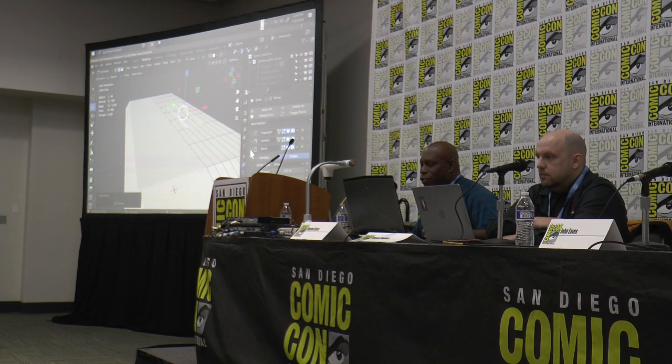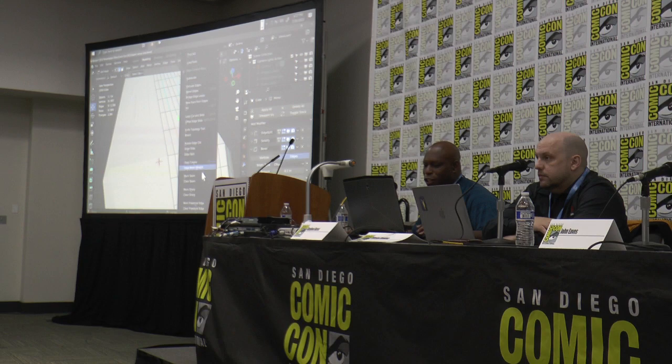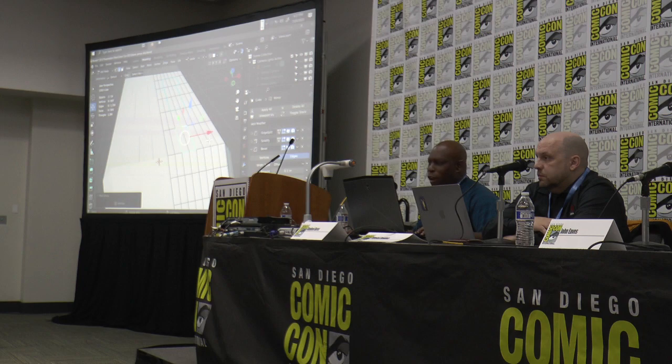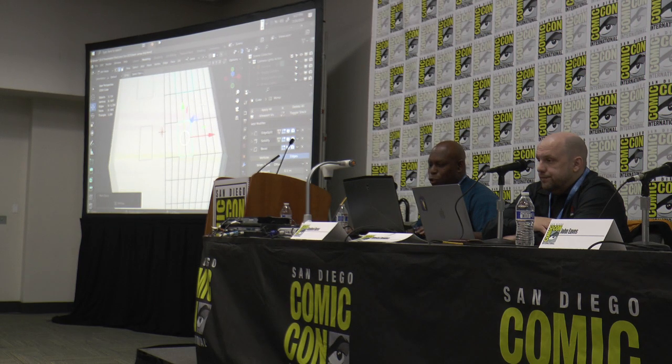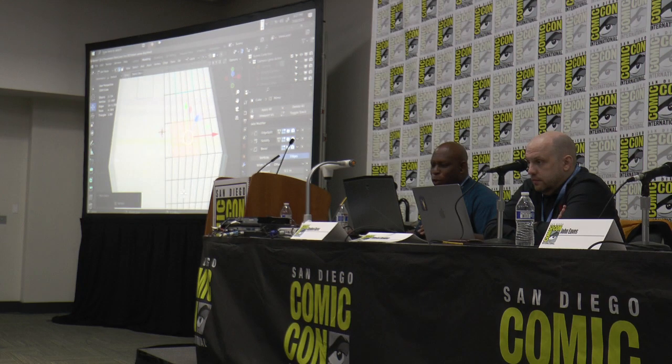So these modifiers, let's do this. Let's do one more. I'm going to show you, say for example, you did something like, let's grab one here, one there, here, and then you came across and you did a mark sharp, but you decided, I don't want that, right? Then easy to do. Just use left click and drag over all those edges, right click, clear sharp. Boom, now it's gone. It's non-destructive, totally. Does that make sense?